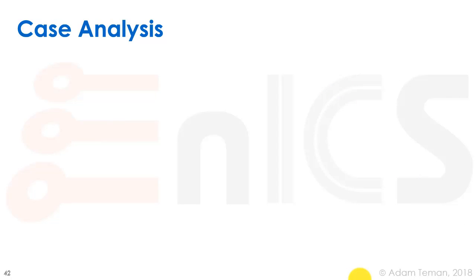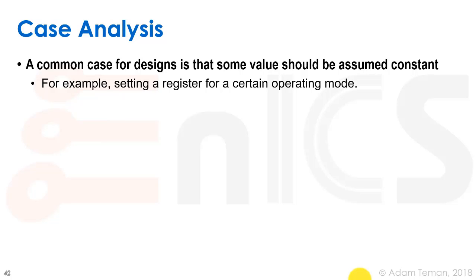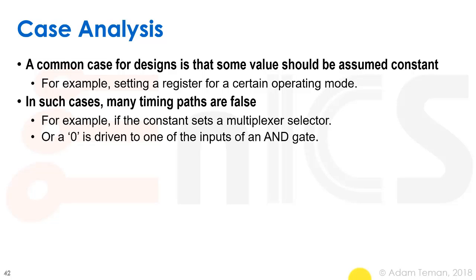Okay, finally we can discuss case analysis, which is a special command that defines constants in our design. There are many values in a design that can be assumed to be constants. For example, if we write a register with a certain value at startup, and then in this operating mode it will be constant, or we hold an external pin at a constant value. What we want is to make sure that this constant is propagated through the tool.